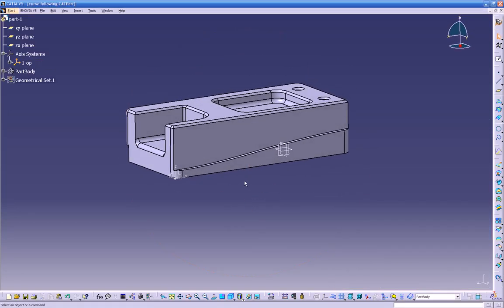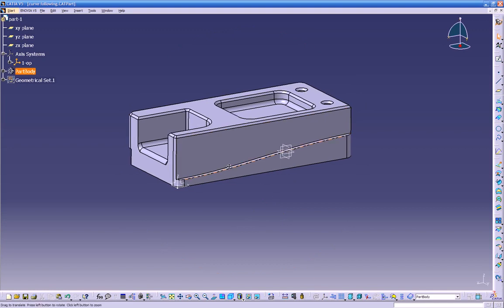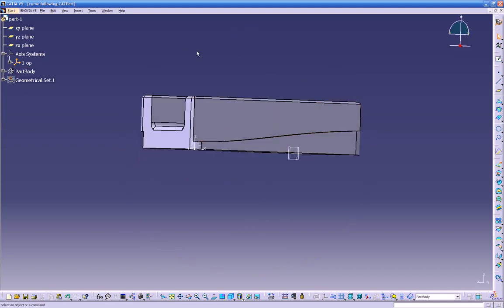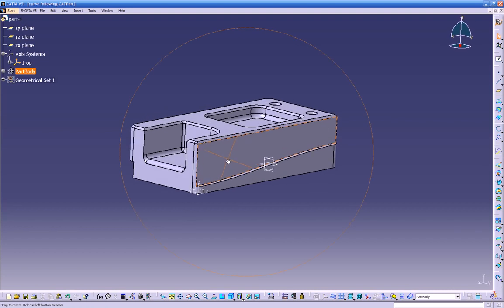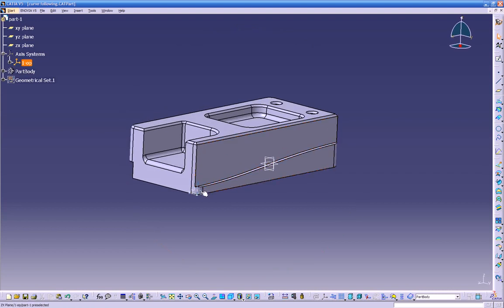And like I mentioned before, every time I create an axis, the very first thing I create is our clearance plane. Clearance plane is where, when the tool retracts, it's going to go up to this plane, go to the next move, and plunge down, and do whatever the tool wants to do. But for now, we have to make sure we create our clearance plane.